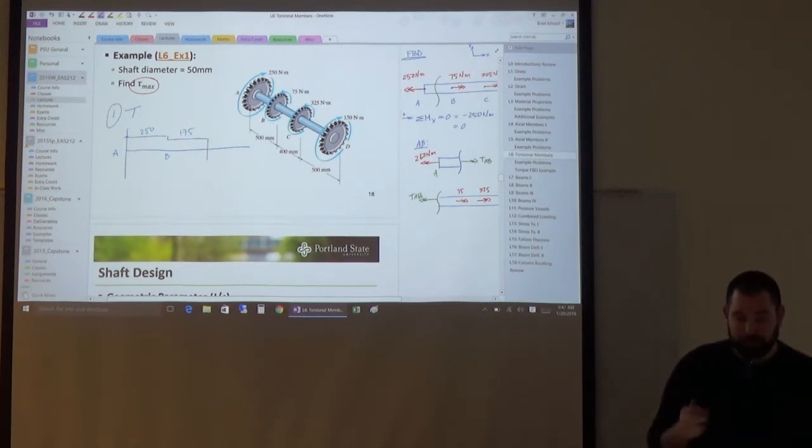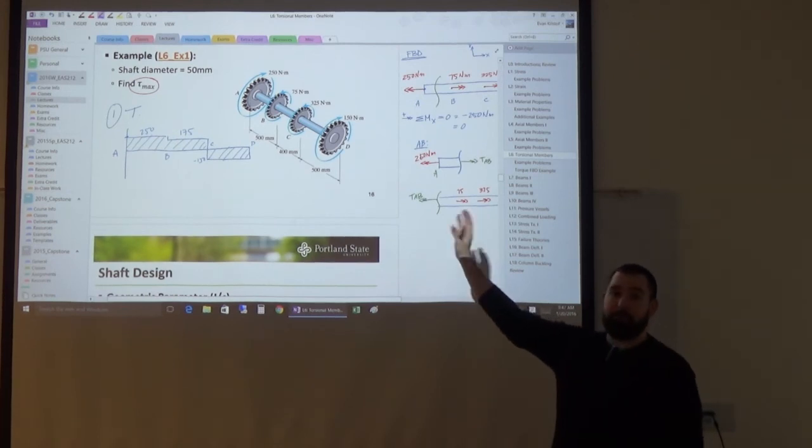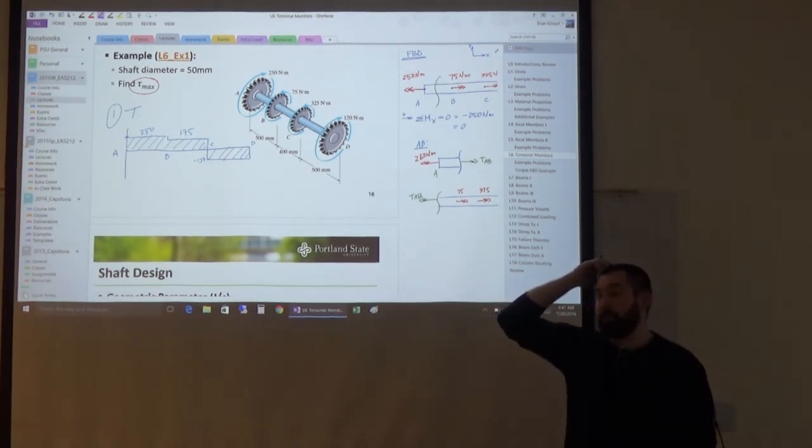It's going to drop down 325 newton meters to negative 150 at point C, and then it'll jump back up at point D to 0. All right, so here's my internal torque diagram, and that would be the best ending point for the first step where you're trying to get the internal torque.